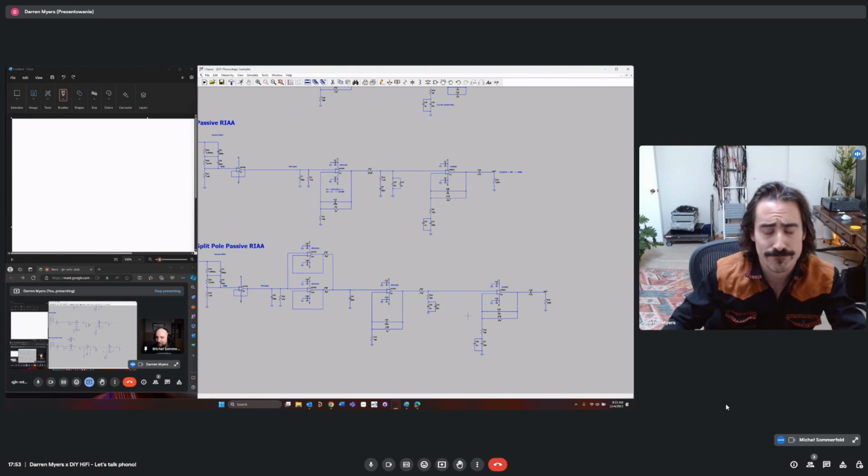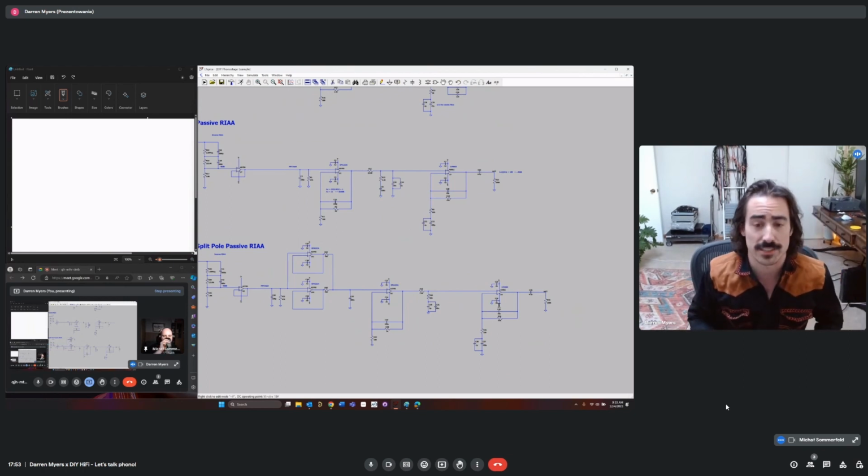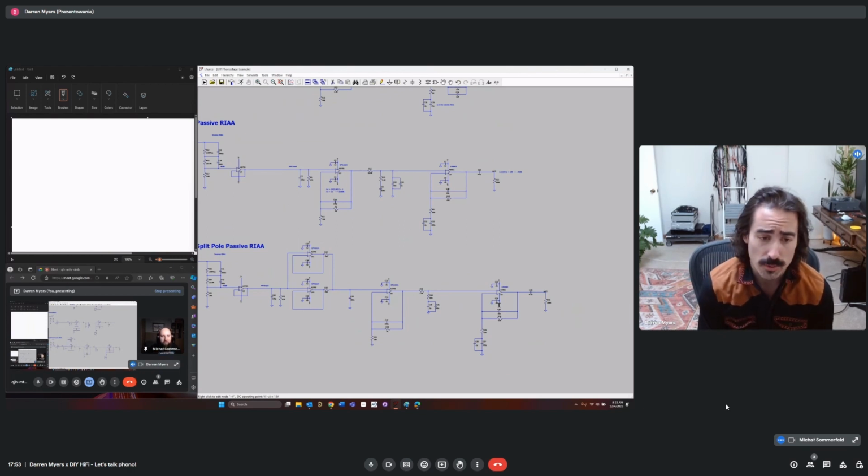Yes. So power supplies and phono stages are obviously going to be incredibly important. We have so much gain that we're applying to the signal that the noise on our power supply is very important. Now, if you're using these monolithic op amps, a lot of these designs have excellent PSRR, so their power supply rejection ratios are very high. So they're going to reject a lot of the noise that is on the power supply, especially in the audio band. And so that is working for us.